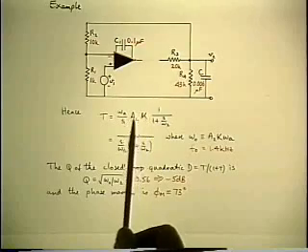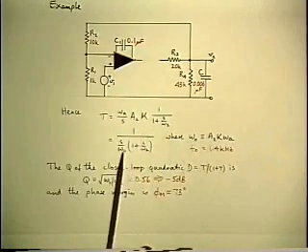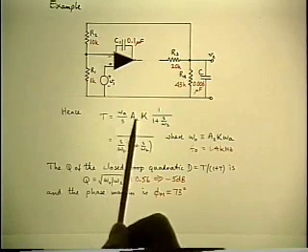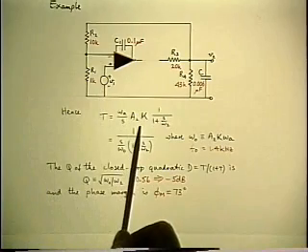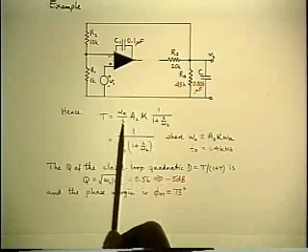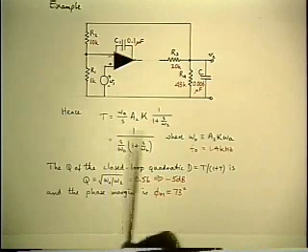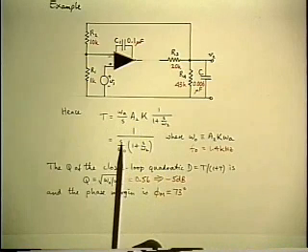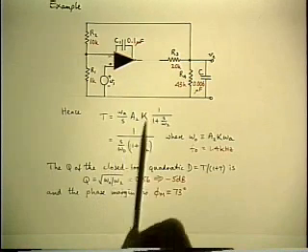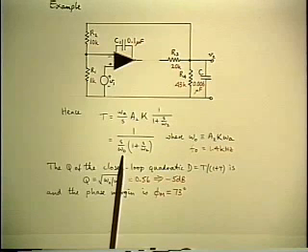So now you get a parameter multiplying these two coefficients together, which you can absorb into the omega 0 coefficient, because we've ignored the fact that there's a zero frequency flat gain, because we assumed the op-amp gain went to infinity at zero frequency, which we know it really doesn't, but it doesn't matter. So that's why the result comes out to have a 1 over S term, and there is no flat gain in front. And the other parameters simply determine what the omega 0 is.